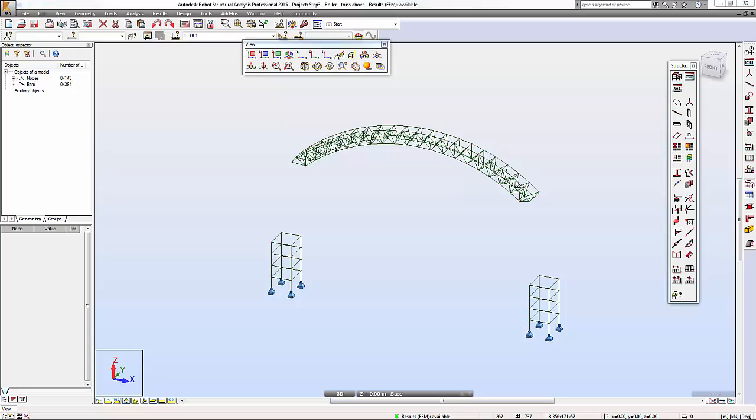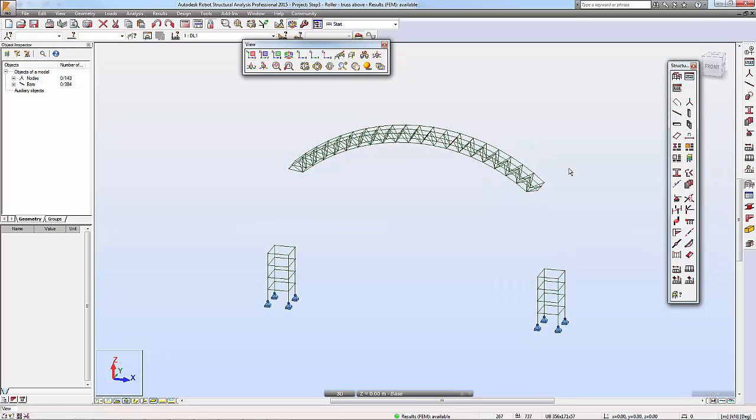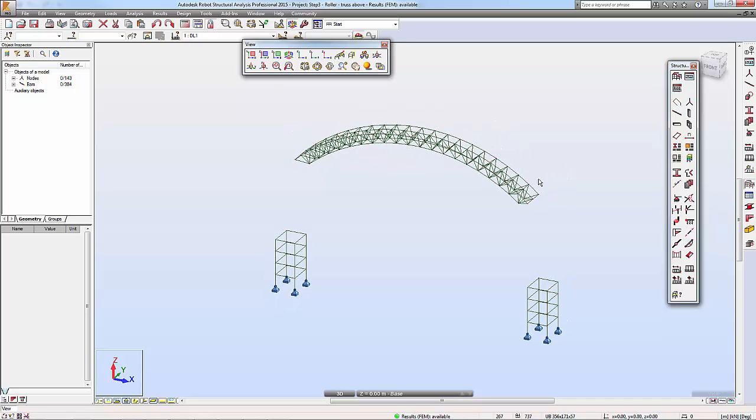And we can see that we actually don't need to put these two structures together, and we can still run the analysis as long as we apply the mechanics relationship correctly between the two joints using the compatible nodes. But somebody may insist, look, I'm not happy about the way it looks. I still want to see the structure connected together, and you can do so, if you want, by moving all the structures down to the proper location. So let me show you how to do this one.